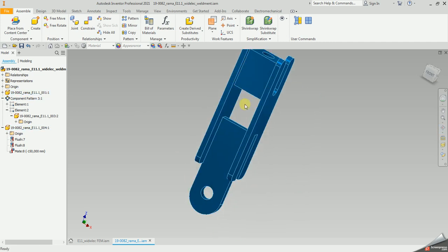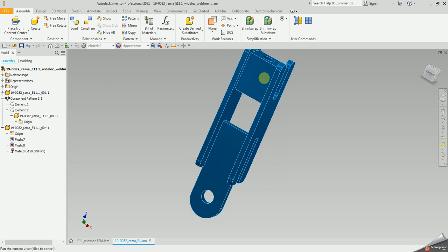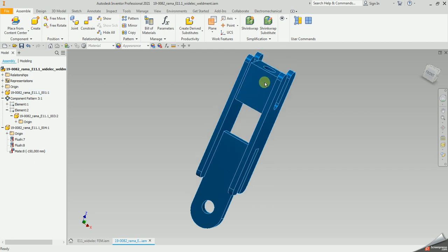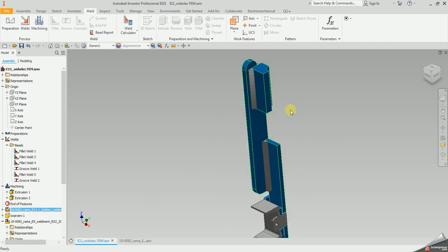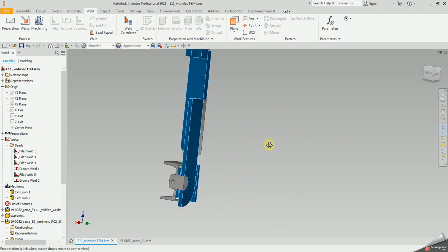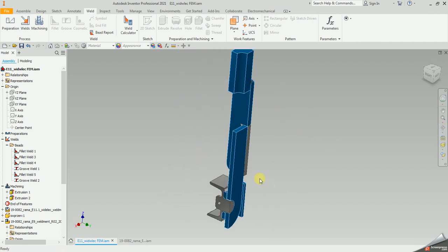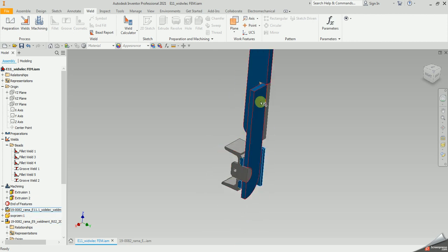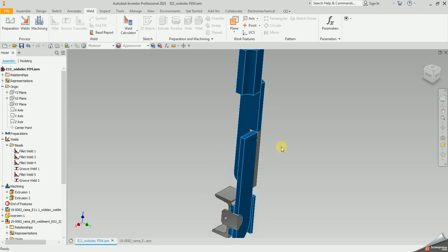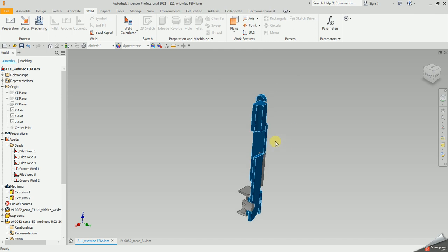There is a pin connection and there is a threaded bar going through this hole, and it takes significant force because it transfers the force from the bar to the pin. And for this purpose I have set up a finite element analysis. It's a quarter, so to reduce the size of the analysis it's a quarter of the element. So we have some fixture here, half of the pin is cut in half and cut also in half the other way as it's symmetrical in two planes.